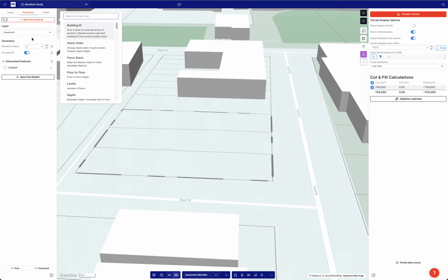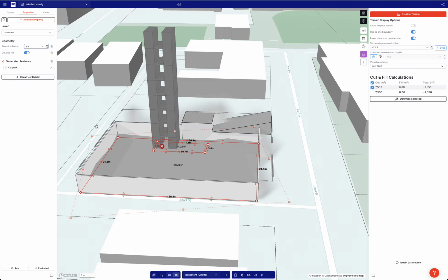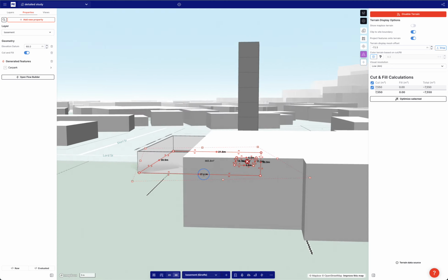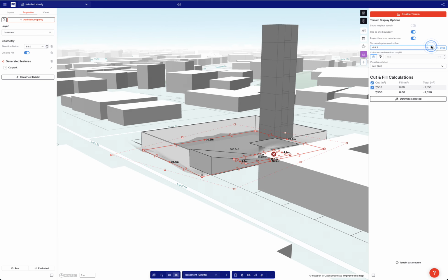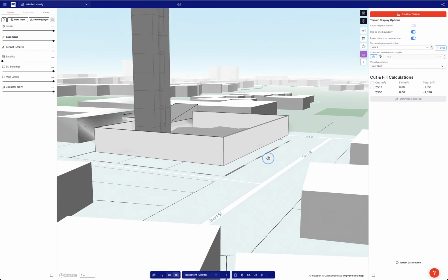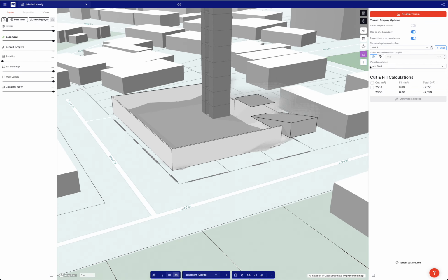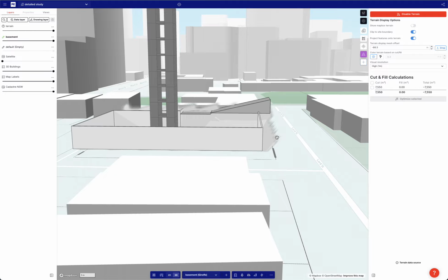And I'm going to set that elevation datum to -68. Or maybe it's 68. Okay, there we go. Okay, so you can see that's slightly underground. So now I'll lift this thing up. You see we've dropped it down, so I'll just lift it up so relatively we can see what's going on. And I think if I change this to a higher, there you go. Okay, cool. So now we've got, oh, and you can see the angle of repose.